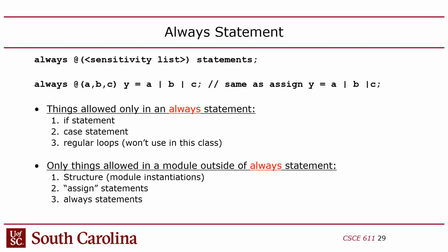I've never found a need to do that. Okay, so this last bullet just kind of summarizes what I've already talked about. The only thing you can put in a module outside of an always statement is assign statements, structure, and then always statements. You guys with me? I know it's hard to remember that, but the bottom line is you can't really put much in a module in terms of behavior unless you wrap it in an always statement. That's kind of the idea.